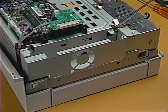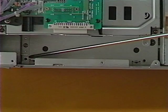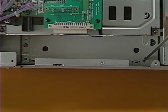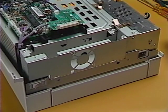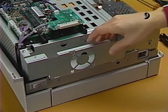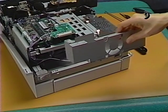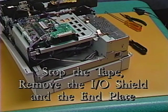Now locate and remove the screws securing the end plate to the printer, and lift the end plate from the printer. Stop the tape and remove the I/O shield and the end plate.